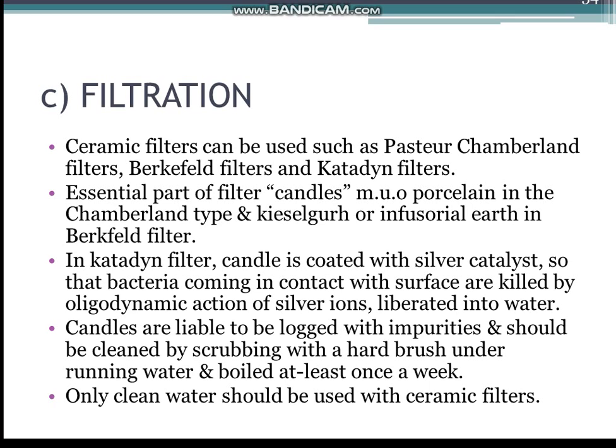Water can be purified on a small scale by filtering through ceramic filters such as Chamberlain filter, Bergfeld filter and Catadin filter. The essential part of a filter is the candle, which is made of porcelain in the Chamberlain type and of infusorial earth in the Bergfeld filter. In the Catadin filter, the surface of the filter is coated with a silver catalyst so that bacteria coming in contact with the surface are killed by the oligodynamic action of the silver ions, which are liberated into the water.